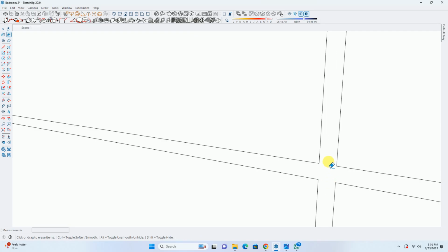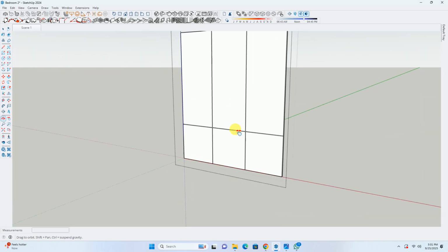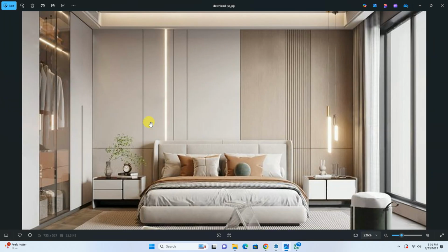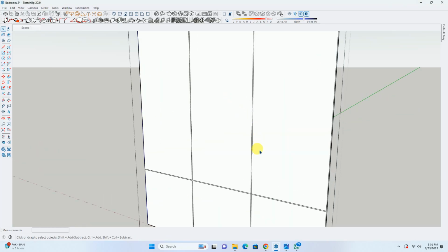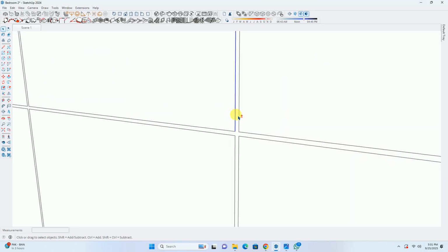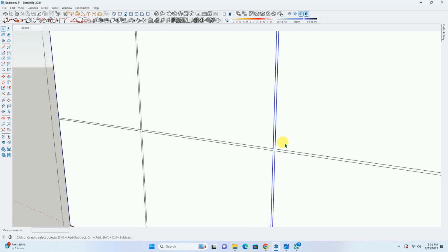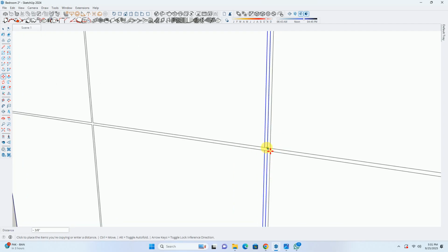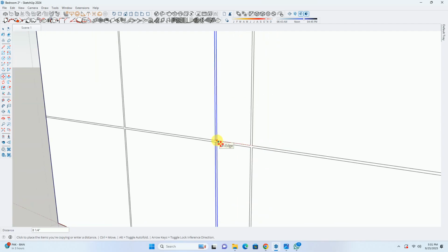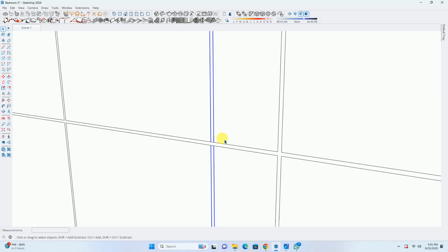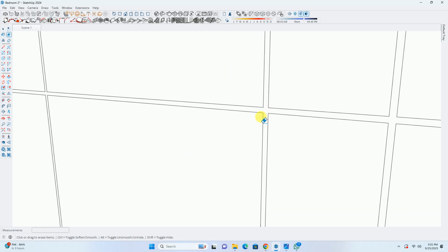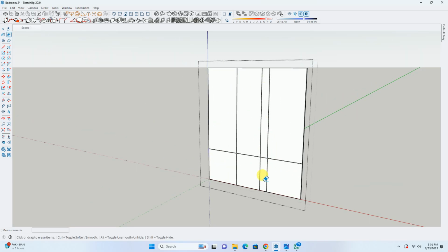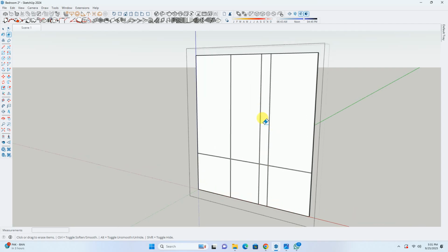We'll remove these grooves, the joints. Now we can see there are two grooves over here in this segment. For creating two grooves, I'll copy all the four lines from this point and create a gap of about 8 inches. I'll remove these boundaries also. And with this we have created our groove.